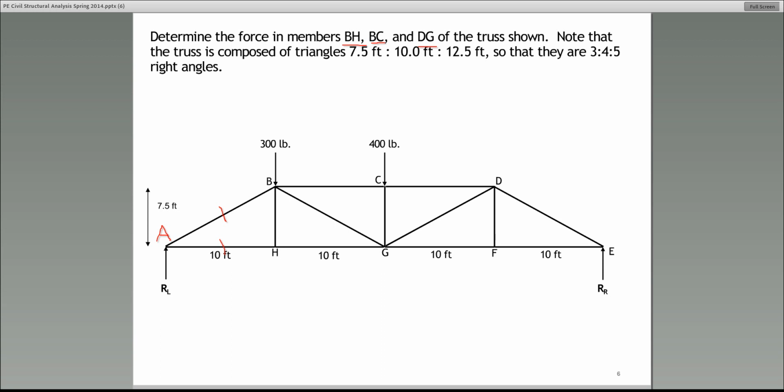All right? Now, there's one other thing that I would tell you. If you are looking at a T section, and this is really important, guys. Now, this is a T section right here. Look at BH. You have member BH, and let me show this in red. You see this BH? That's a vertical member. And then you have AH moving all the way to HG. This I refer to as a T section at the point H.